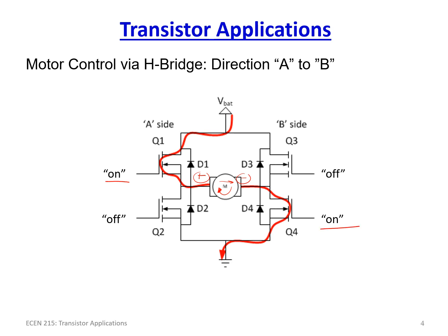We turn on this transistor, and current is going to flow in from VBAT, say if we have a battery here, and it's going to go through this transistor, go through the motor from positive to negative and turn clockwise, and eventually return to the negative post on our battery. And that's exactly what we want. And notice the other two transistors, in this case Q3 and Q2, are both off.